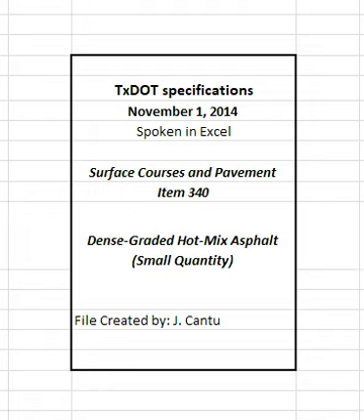Use an approved laboratory from the department's MPL to perform the Hamburg wheel test in accordance with Tex-242-F, and provide results with the mixture design, or provide the laboratory mixture and request that the department perform the Hamburg wheel test. The engineer will be allowed 10 working days to provide the contractor with Hamburg wheel test results on the laboratory mixture design. The engineer will provide the mixture design when shown on the plans. The contractor may submit a new mixture design at any time during the project. The engineer will verify and approve all mixture designs, JMF1, before the contractor can begin production.